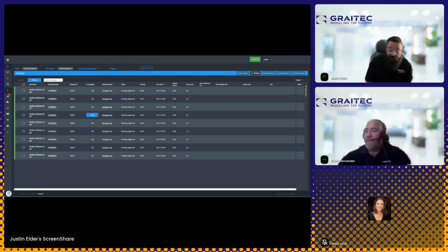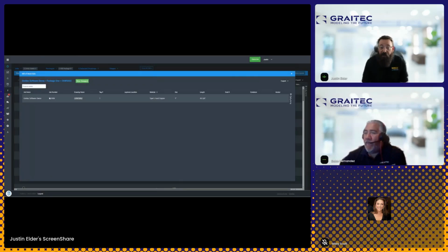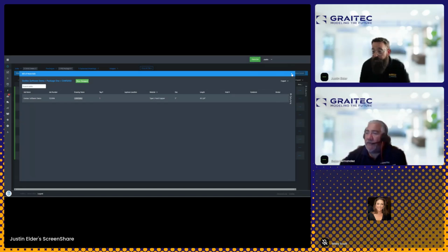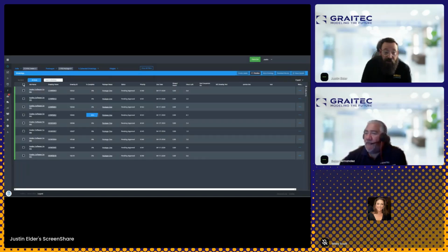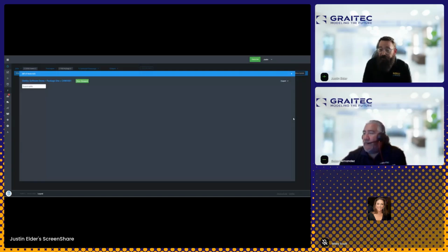Right. So even to the point where, like I mentioned, as easy as it is to create a BOM list, all I have to do is come in here to the package name, click on my 3 buttons over here. I click View BOM, and it pulls up as easy as that. So all I have to do is click in here, and now I've got an easily accessible export to a CSV for my distributor. And it doesn't have to be individual too. I can highlight the entire packet or the entire drawing level or the entire package level, and do the same thing.